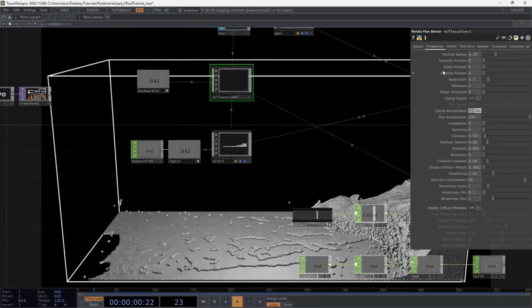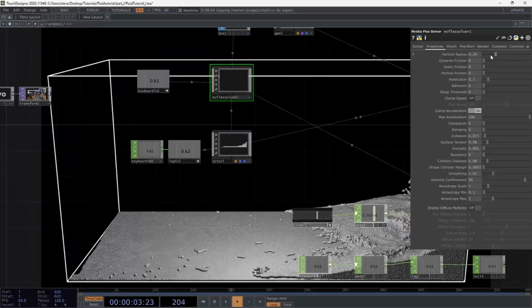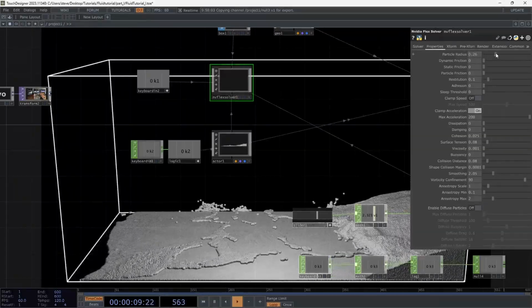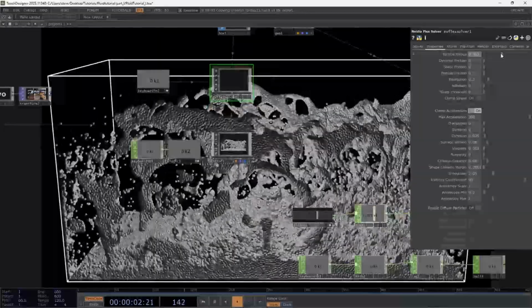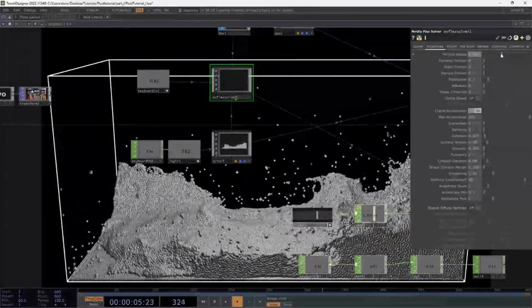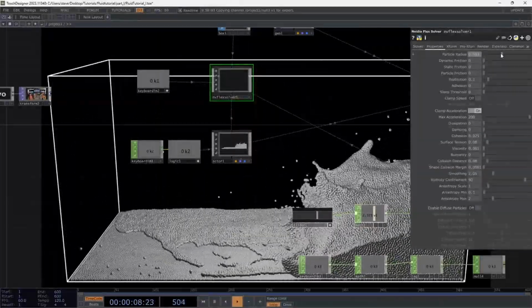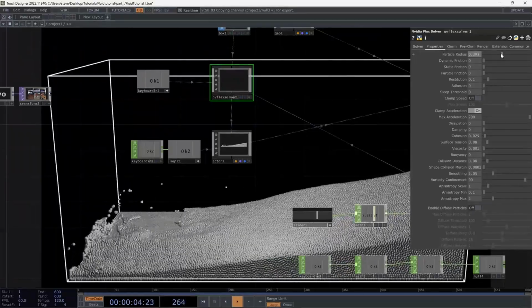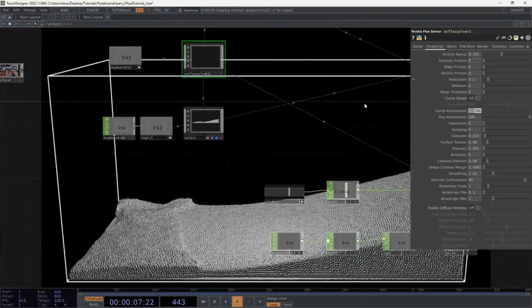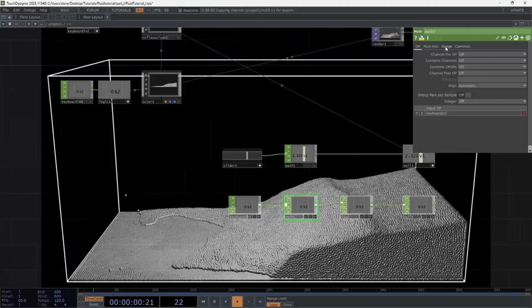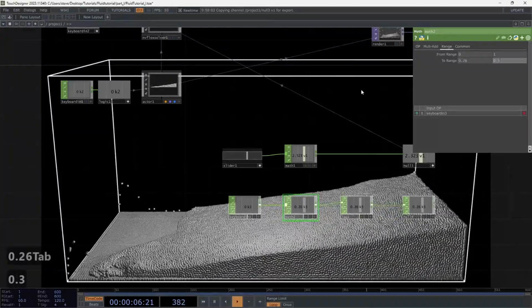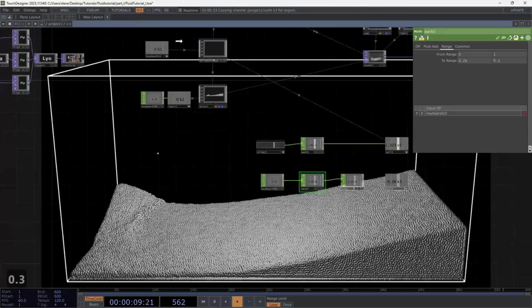So now in the properties of the solver, particles is very interactive, the radius to change this. If I go more up, you can see the radius of the collision is getting larger, so each of these balls are also going further away. Just changing this, maybe from 0.26 to maybe 0.3, maybe that's already enough. So let's just hook this up.